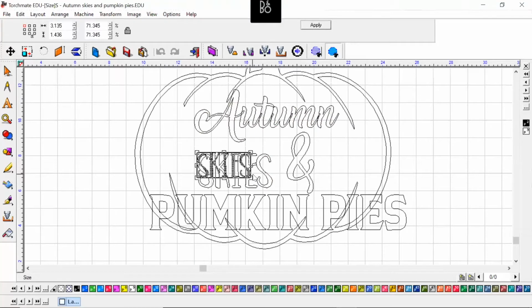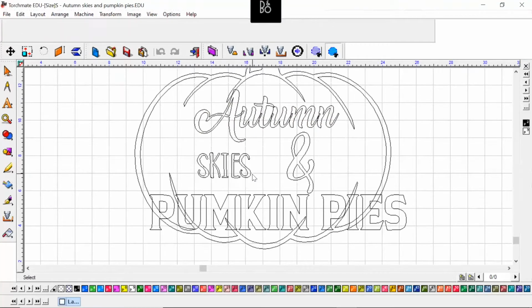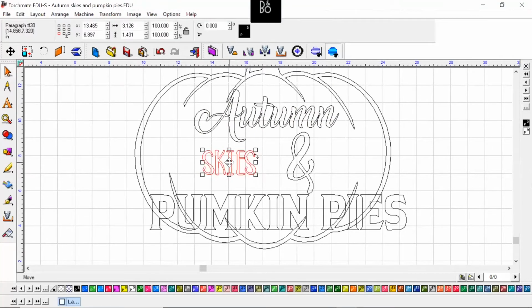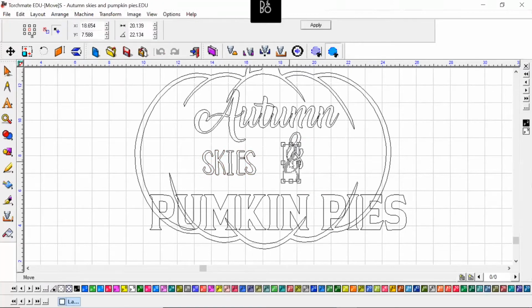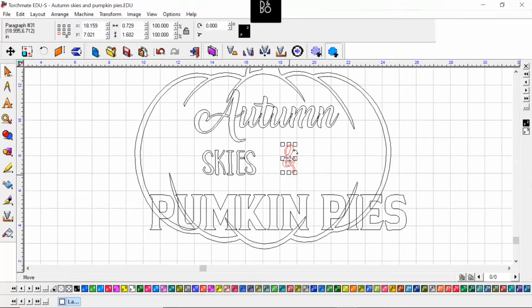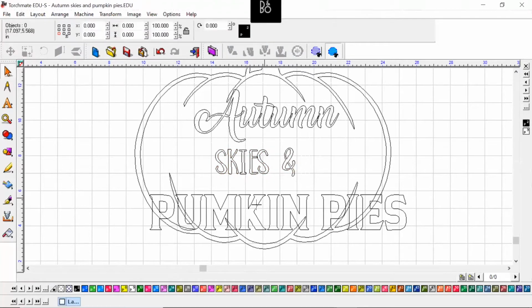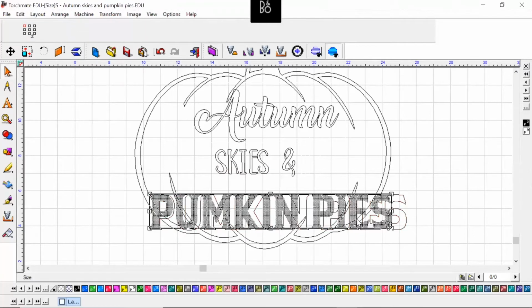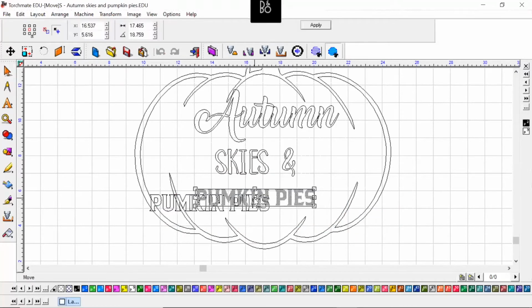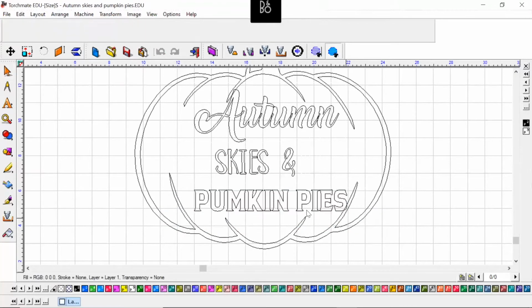With your letters, you don't really want to go too much smaller than, let's say, 3/4 of an inch, 1/2 inch or so. When they get that much smaller, it starts to run into issues out in the machine when we're cutting and all the little bridges and everything we got to fit in there. I have those about the same size. Bring this guy down.